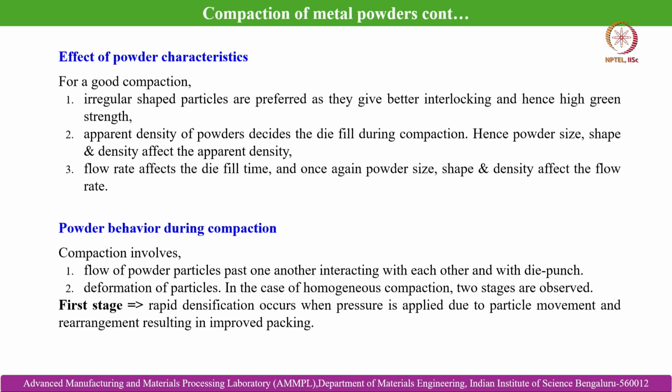So the apparent density of powders decides the die fill during compaction. Hence powder size, shape and density affect the apparent density. Flow rate affects the die fill time, and once again powder size, shape and density affect the flow rate. So, the powder behavior during compaction: compaction involves flow of powder particles past one another, interacting with each other and with the die punch.